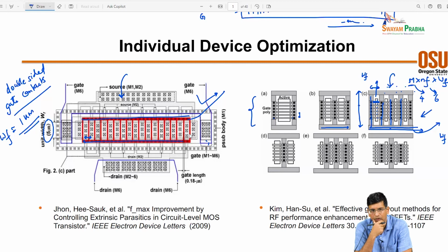Not to my knowledge. The PDKs themselves do optimize; double gate contacts are available. There are some PDKs that let you set the pitch of the gates and the number of fingers that you have. PDKs will sometimes enable M1 or M2 routing, and tell you what layer you can bring it up to. So that is available, but this type of thing, no. You have to lay it out and do it yourself.